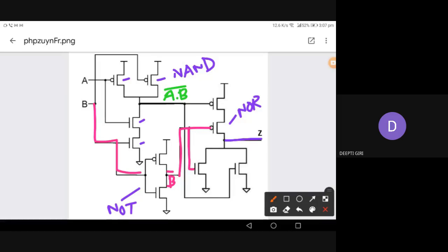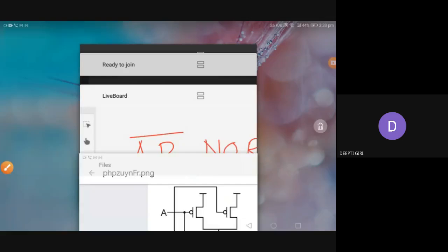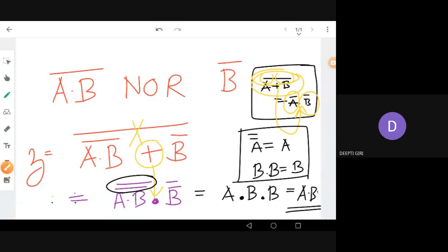This is going to one PMOS and one bottom NMOS, right? So I'm NORing what? The NOR gate has the inputs A into B bar and B bar, right? So I'm just simplifying that. I'm just NORing these two things, A into B bar and B bar.